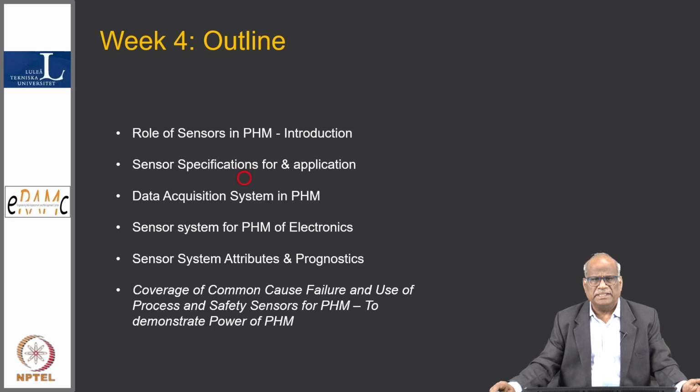And then the third is the data acquisition system, because from the sensor onwards, a data acquisition system is concerned. Of course, there is a transducer in between, whether it is part of the data acquisition system or part of the sensor, but it is required because we have to convert any signal, pneumatic or hydraulic, or any degradation mechanism information that is coming in, into an electrical signal. So transducers are very important. Transducers are even sometimes called transmitters in process language parlance.